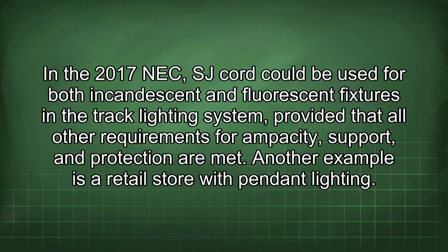In the 2017 NEC, SJ cord could be used for both incandescent and fluorescent fixtures in the track lighting system provided that all other requirements for ampacity, support, and protection are met.